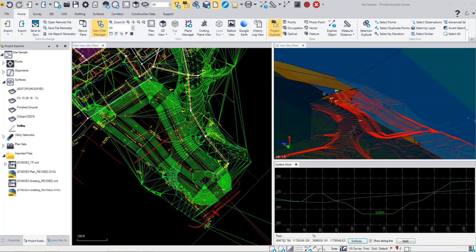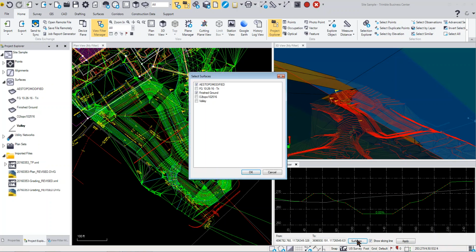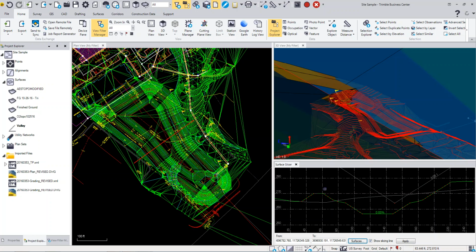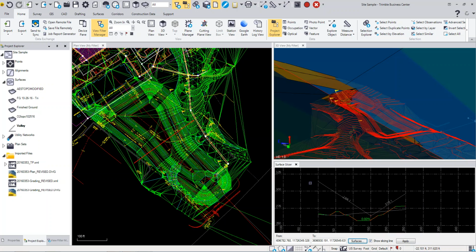So you can see that the surface gets created. Again, the best way to see this is in the surface viewer. So I'm just going to pick valley, and you can see here what that slope looks like in there. So we went out basically holding that elevation, went that way. So that's a planar surface, planar slope. So we could go negative slopes to go back the other direction, but it's kind of a quick way to create just a flat plane surface with no real details.